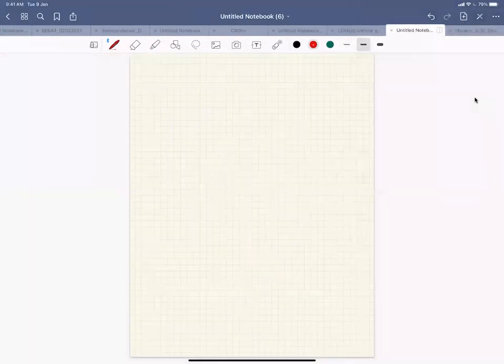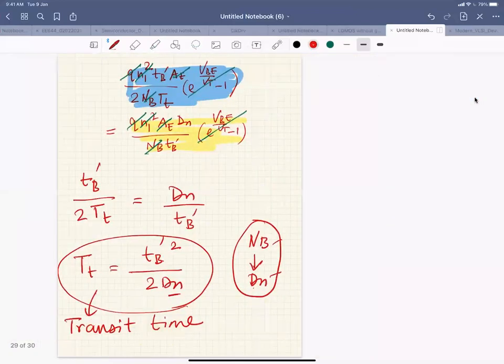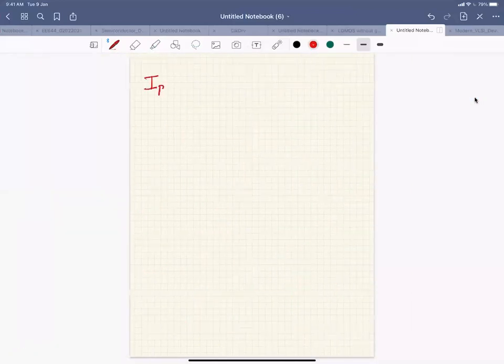But again, if I want to find the base recombination current IBR, recombination, if there is some excess charge, this is QBN. This is the total charge I have, delta QBN times AE, by tau n, right? So your IBR recombination depends on this minority carrier lifetime, tau n, and the excess carriers.